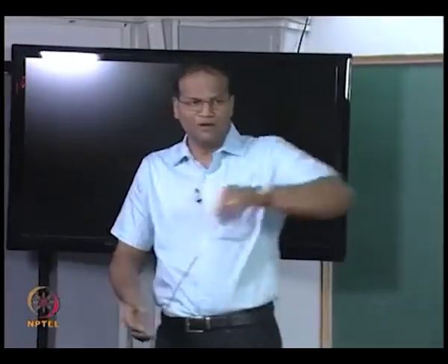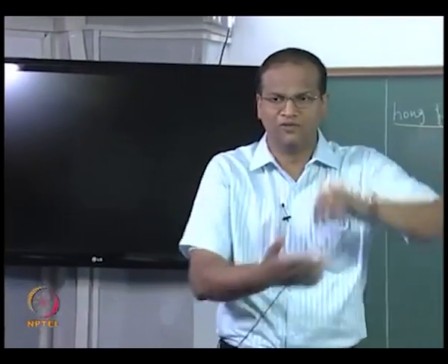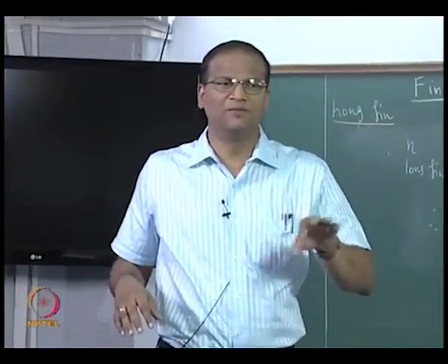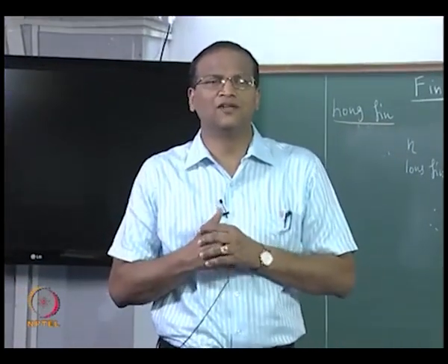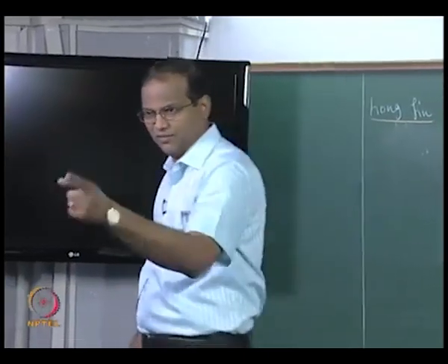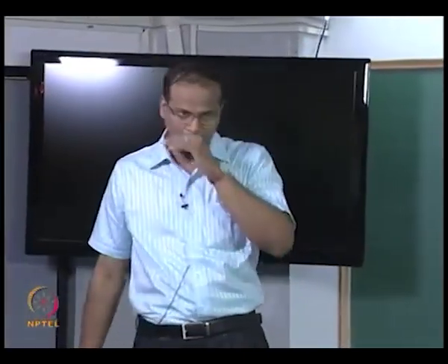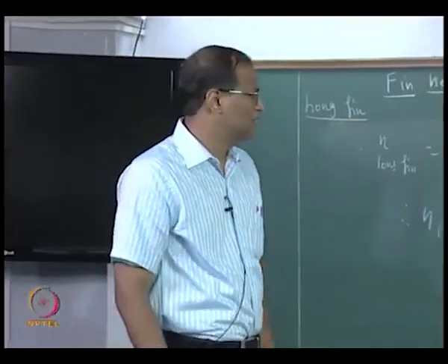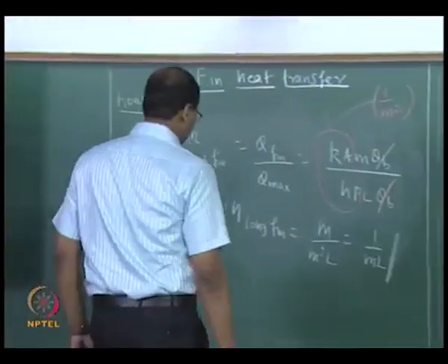Instead you can cut them down and crowd the base with more fins. Of course that may locally affect the heat transfer coefficient, but you can put some fan, increase the velocity and do something. That is what I showed you, the heat sink with a fan and very closely packed fins. Alright. Now how long is long? That question has to be answered.